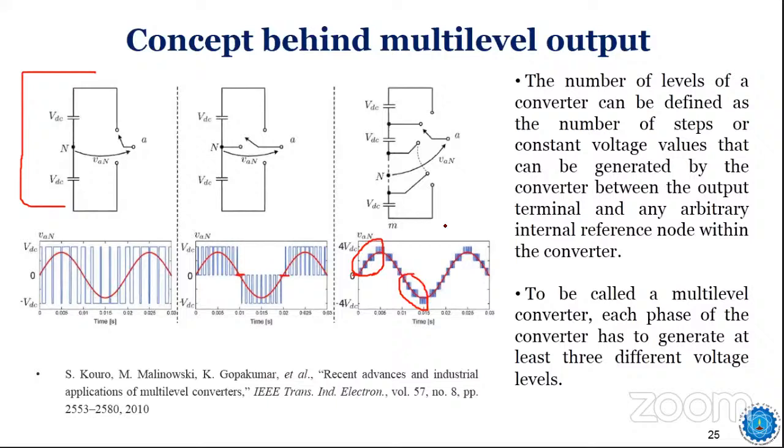Okay, and with this type of output, when you increase the number of levels, the output gets nearer to the sinusoidal. That is the reason the output of a multi-level inverter contains lesser harmonics. If you check the total harmonic distortion, which is a factor used to decide the harmonics present in the voltage and currents, and calculate the THD of the output voltage of a 3-level inverter, you see the harmonics will be much more than with this multi-level type output, right? Here the harmonics will be reduced.